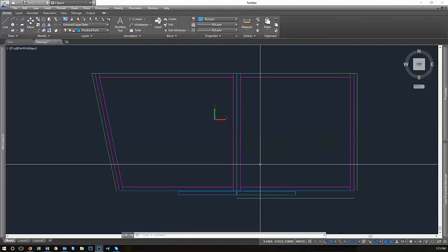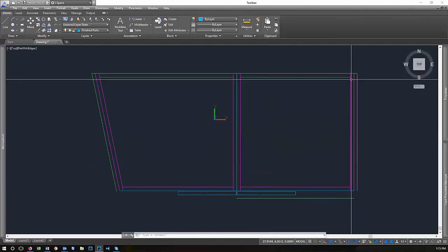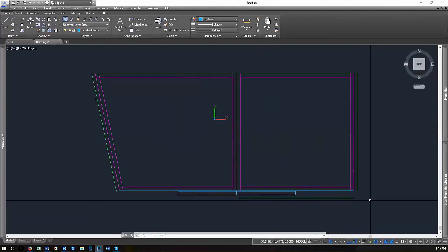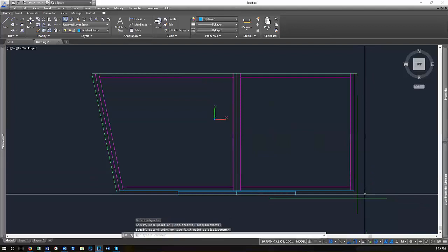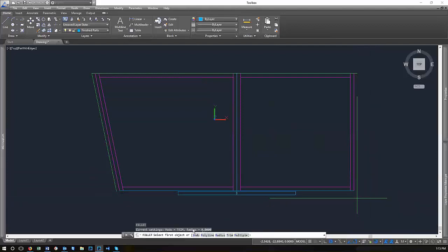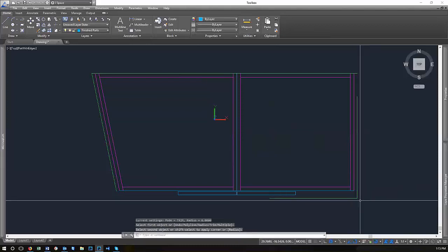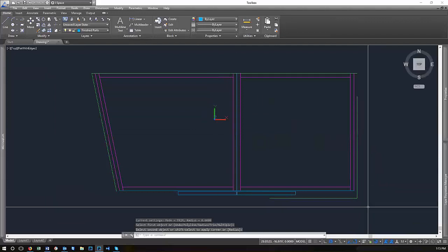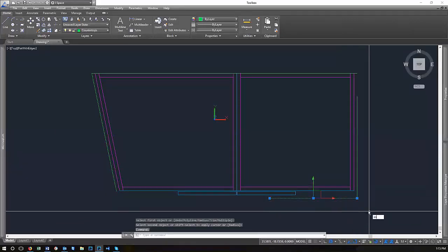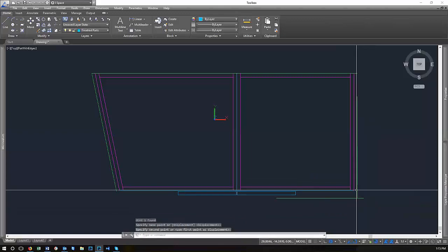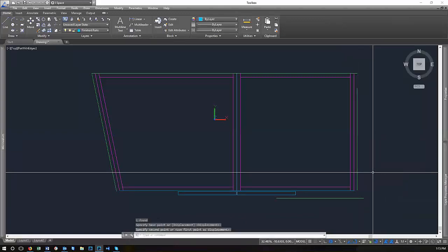So now I'm going to do the fillet command again. So you saw it extend two lines. So now let's move this line over here. Move this line over here. You can use the fillet command with 0 radius to bring these two lines together. So that's like a trim command. So that was an extend, this was a trim, and then if you have a situation like this as well, it can do one of each.